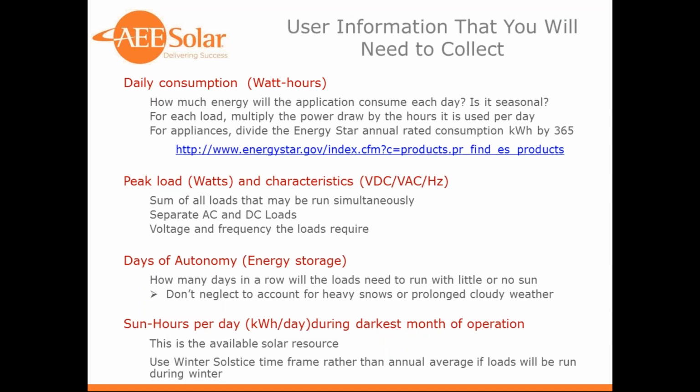So here's some of the information that you need to collect from your customer in order to properly design a system. And the first thing we need to look at is what the daily consumption is, or at least an average daily consumption. And this is, how much energy will the application consume each day? And is that seasonal?